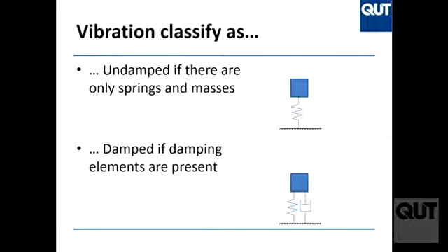I mean, it oscillates also if there is a damper, possibly. It never stops. It oscillates forever. In theory, if there is no damper, the system will oscillate forever. In practice, does this case ever exist? No, it would be perpetual motion. There is always a little bit of damping.